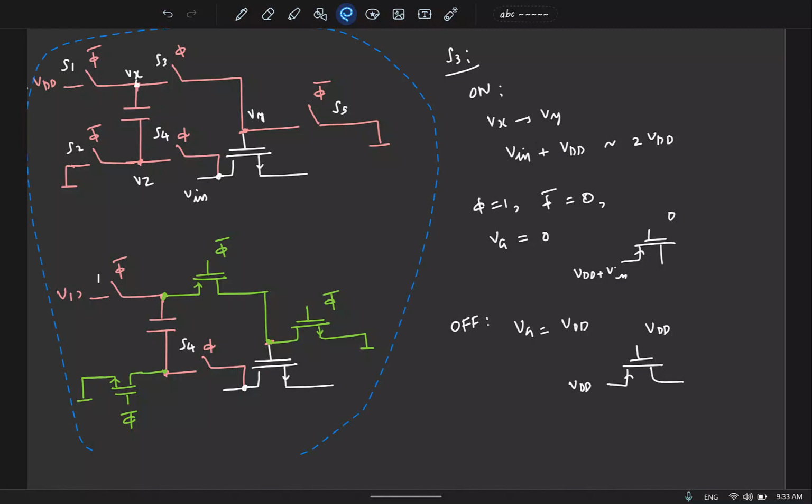So what's the problem? The only goal of this guy is to keep the VGS constant and equal to VDD, right? When the switch is off, we'll have the case like this. The capacitor will be charged to VDD. If it takes some time to charge, let it charge, right? But the moment you connect it here, this is acting like a battery. When this voltage increases, this will instantaneously increase. There will be no delay. This is like a battery. So the moment Vin changes, this guy will also change instantly to VDD plus that voltage. Let me actually.